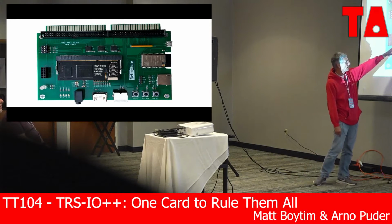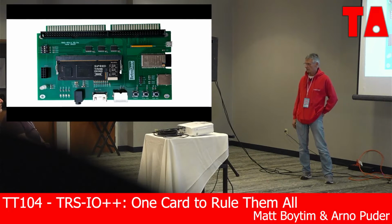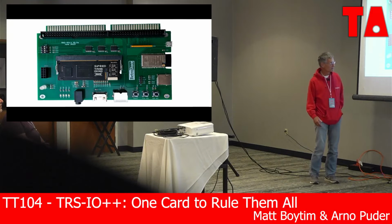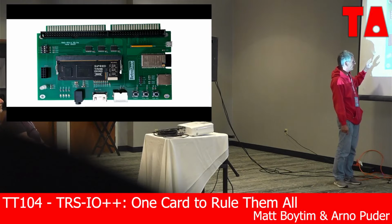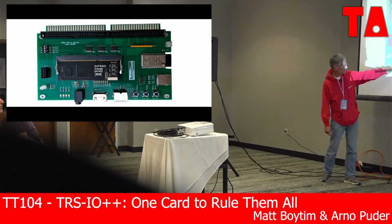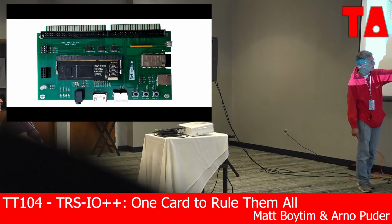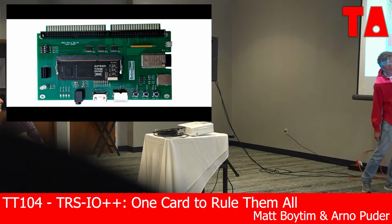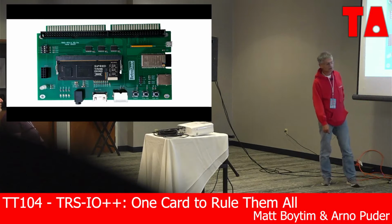So in the middle we have the FPGA, which is a Sipeed Tang Nano 20K. 20K means about 20,000 logic elements. It has some additional features, internal RAM, and so on. This is the PMOD connector. The TRS-IO has traditionally had an RGB LED, which is located here. That's the cassette in and out connector. We have the HDMI connector, the keyboard, some push buttons, SD card socket, the ESP32, and then we have the 2 expansion connectors at the top, both the headers and the cartridge connectors.